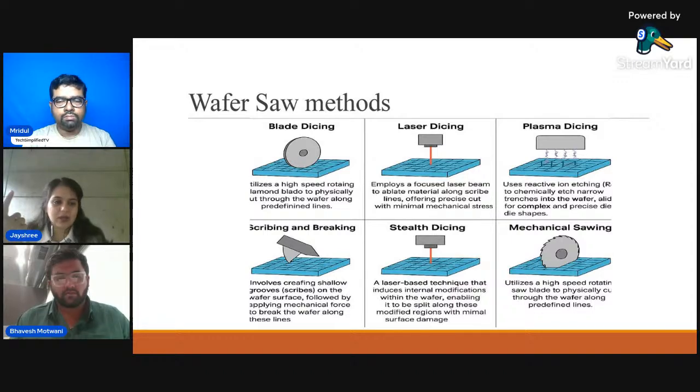In plasma dicing there is no mechanical or thermal damage, it gives clean edges, and it is basically best for ultra thin films. The con is that it's a complex process, because generating the plasma is again a long process, and eventually it's higher cost, as plasma generation has a more complex structure. So yes, it's higher in cost.